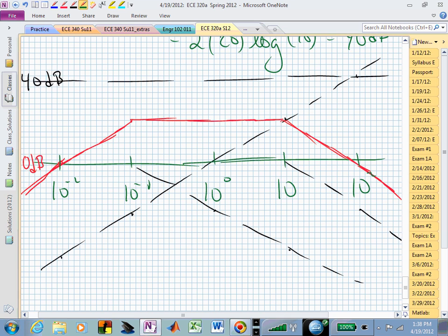Is that making sense? And what are we doing with quadratics? We are going to approximate those in this class. It's not what's really happening, but just to get us sketching, we're going to roll that all the way around. We'll keep it on a string and keep the natural frequency the same and roll it down to become two real poles. Instead of two complex conjugate poles, we'll roll one down and one up, and they'll both be real, and then we'll treat it as an s over omega sub x plus 1 quantity squared.